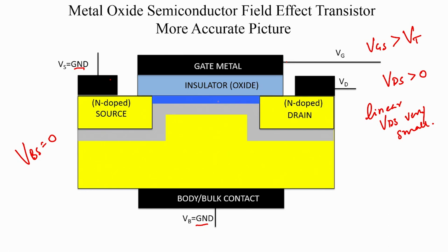And if you remember the band bending, let us take a cross section like this through the MOS capacitor. So, you have your gate metal. Let us say we start from point A and head to point B, and we are going to draw the band bending along this cut line. At A you have your gate metal, which has a certain work function.